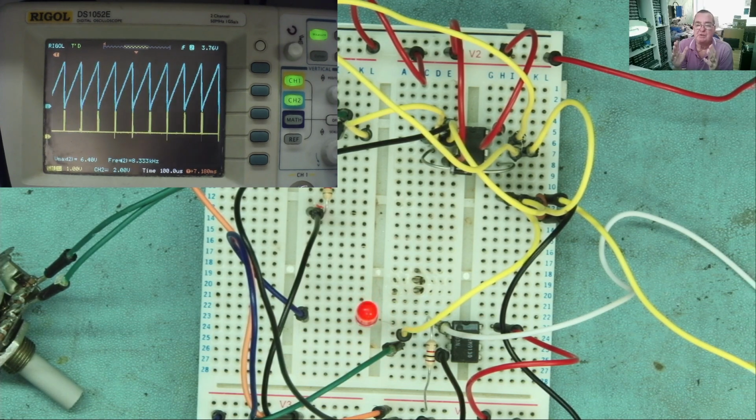And especially if you get, for example, a short circuit on the output of a power supply, it can damage the power supply. A short circuit on the output of an amplifier can damage the amplifier. So if you've got PWM based circuits that are giving no output or just blowing fuses when you plug it in and such like, the first place I would be looking at is the output devices, yeah?